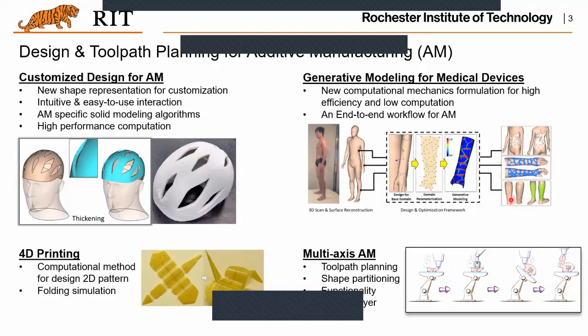All right. So the last piece of the research is the multi-axis additive manufacturing. For the traditional additive, basically you are printing in one direction. Once you decide what is the printing orientation, there's no way to change it, right? But that brings problems. For example, the support material. Some geometries have a facet facing downward, and that's not desirable because you have to print some support to support those regions.